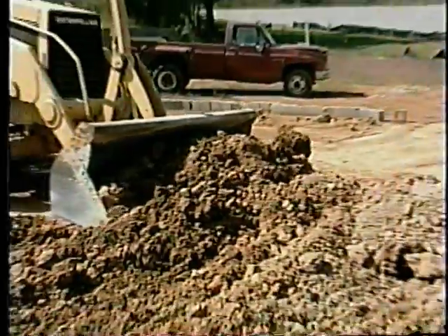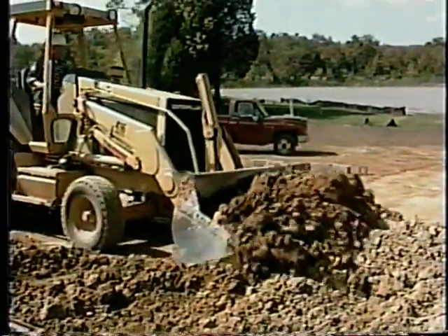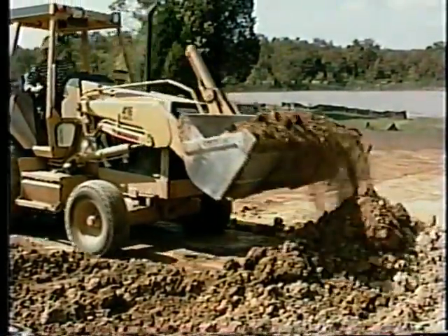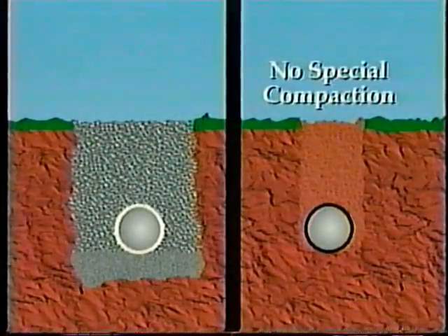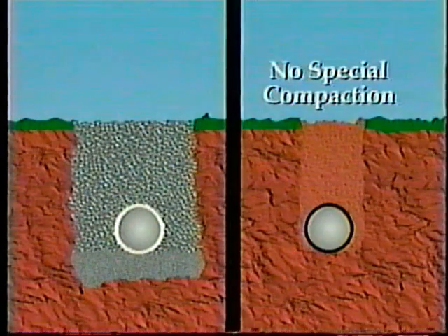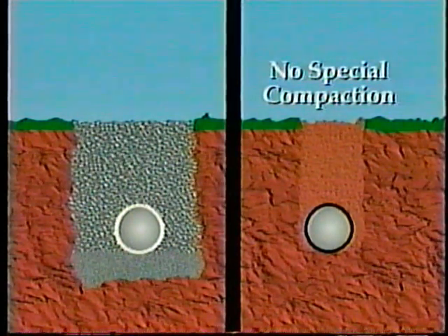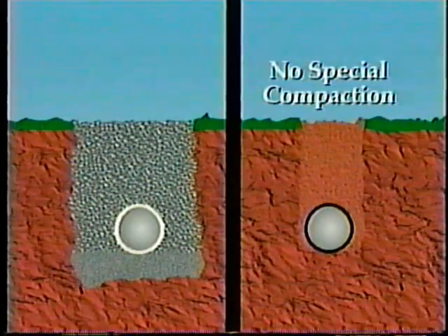Once an underground pipe is installed and inspected, it must be backfilled. With cast iron, no special compaction of the backfill is necessary, except for meeting the normal compaction requirements of the excavated area. Since cast iron is a rigid material, it does not depend on side fill support, although sometimes installers may use a small amount of granular fill to improve the grade.